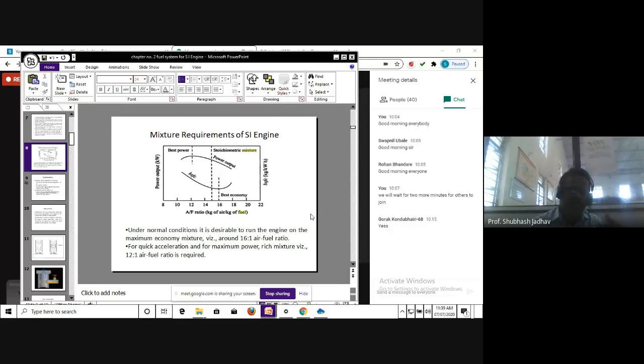But if that particular fuel is unable to convert into vapor easily, that is, it has poor vaporization characteristics, then we will not be able to complete the vaporization process in the available time, and the fuel which is going to the combustion chamber will not be complete vapor, but it will be going in the form of liquid droplets. And we know that once our liquid droplets are going in the combustion chamber, they may burn or may not burn, we cannot ensure. Because we have designed the system for burning the air fuel vapor mixture.